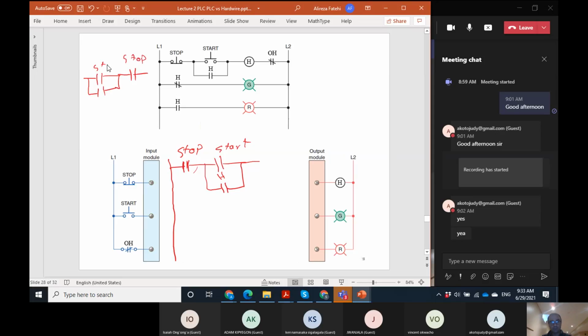Stop, start, and edge. Okay, so there's not any difference. These are series connections. But regarding the edge here, in fact, this is the heater. This is an output contact. In the PLC program, most PLCs require the output coil, or the output assignment coil, to be on the right side of the program. So not in between. So this is here.